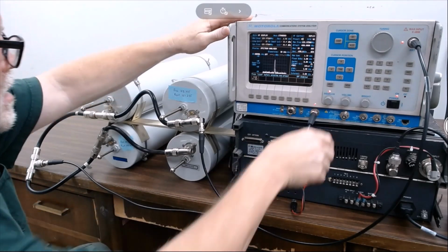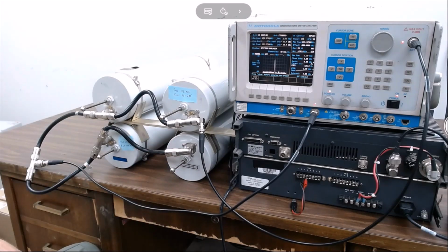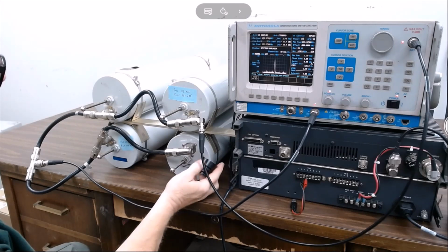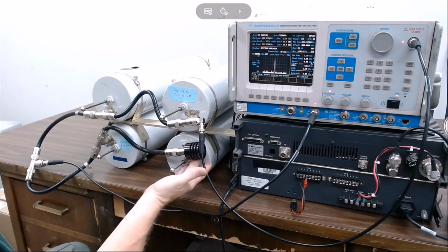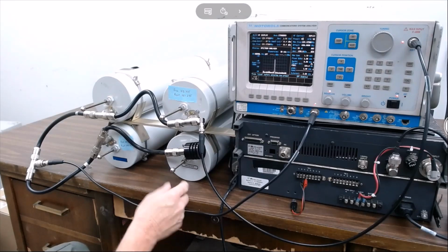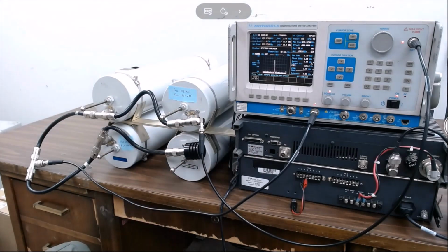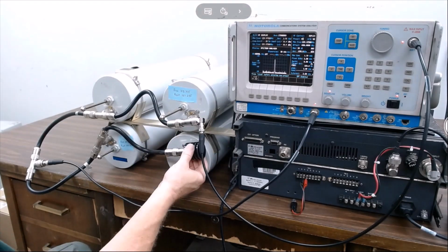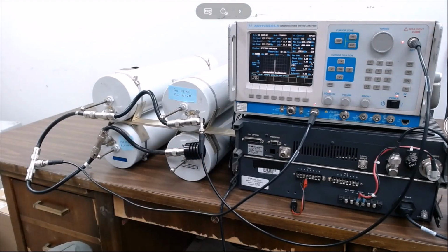But you see the idea of what I'm doing, and I'm going to do the same thing when we move down to the other one, just a back and forth. And I can see right now, if you're wondering, does this part of the duplexer need to be terminated or not? I've tried it both with and without, and it's really immune to it. It doesn't seem to notice it at all. In general, though, if you are working on any kind of RF devices that should be terminated and they're not, go ahead and terminate them so it balances everything out to 50 ohms.